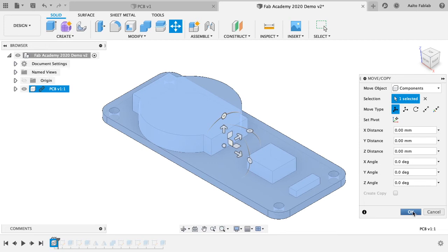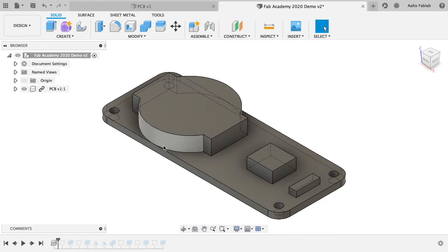And it's going to insert it as a component. And a component is an interesting concept in Fusion 360, because a component has the same things that we had on the root hierarchy when we were building the object, which consists of an origin and then bodies and sketches. So the most important part of the component is the origin, so that it has its individual origin, which is being used by the bodies and sketches inside the component.